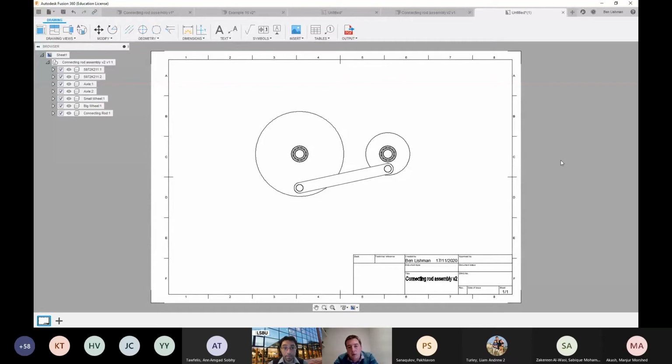And that's got all kinds of details, like where would they have to position the drill bit, or what size of cut would they have to make from their initial material. That's what a part drawing needs. An assembly drawing assumes that you have all the parts already. So here, what I need to show somebody is what are these parts and how do they all fit together.